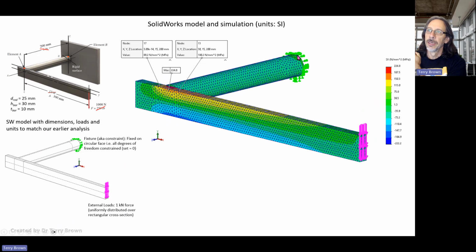If you draw this line on the top of the cylinder, come directly up along the back side of the rectangular bar and then across the top, then where that line intersects with the longitudinal line down the middle of that top face, we get this point here. So according to this original diagram, that's where they're referring to element A.